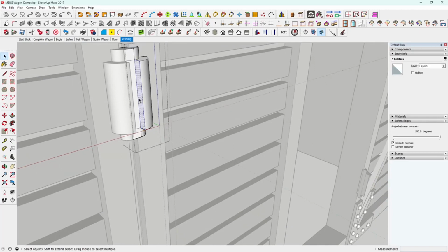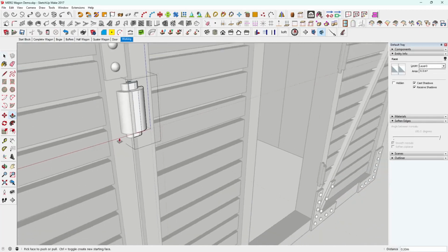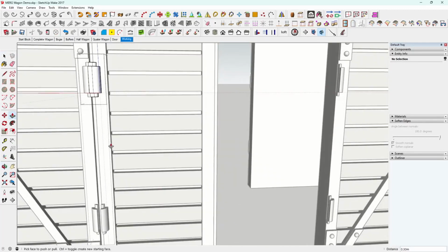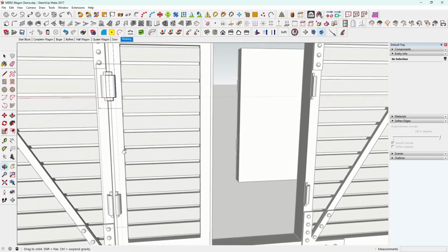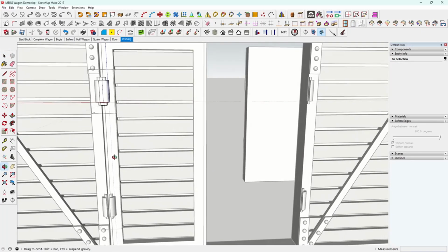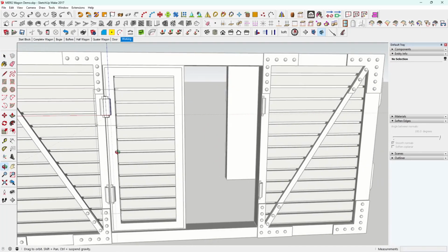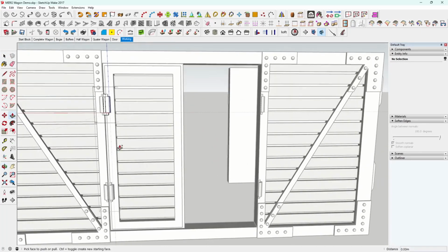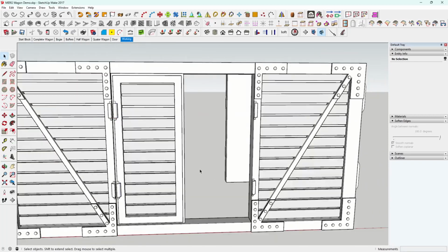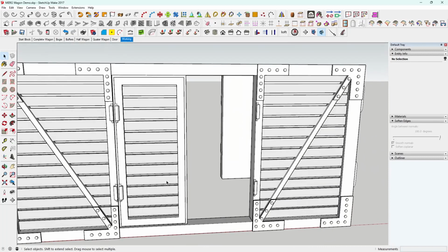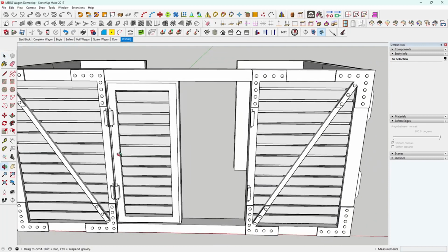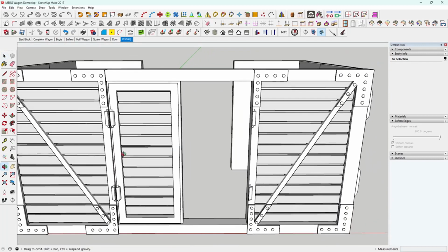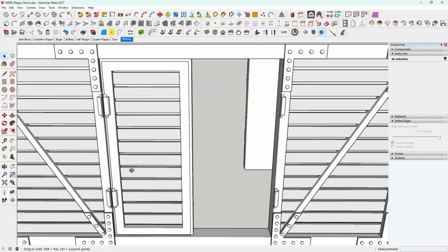Same with this face, just pull it across, and then you sort of join the hinge up. Really depends what you're going to do with it. So you could have two versions of the door if you wanted. So we'll do a Control Z, we'll leave it as a separate door, and if you pose it in the opening position or whatever, you can just turn it round.